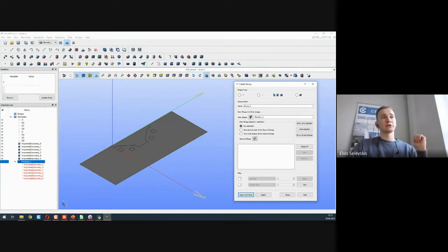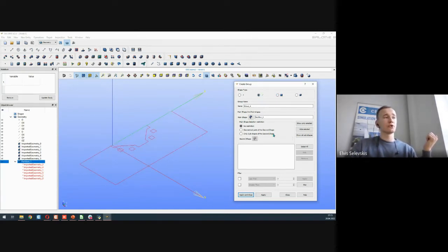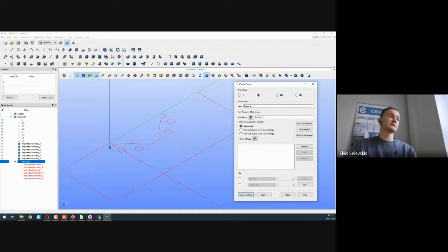We can select the faces, which will be needed for the 2D faces which we have, and also the lines which will be needed for the workpiece interface, similarly as you would have in 3D simulations, as well as workpiece symmetry, in this case air symmetry and air infinity.